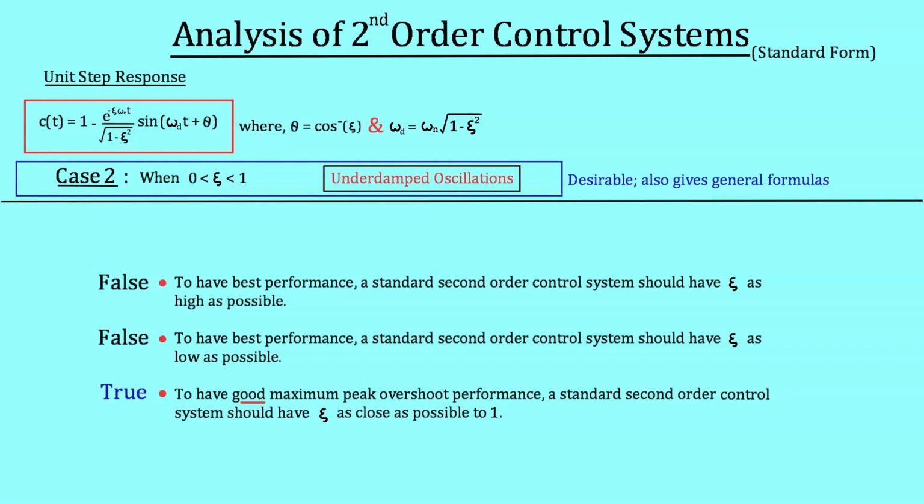If you are confused about the other parameters and what the ideal value should be, then let me tell you, the ideal output profile should look exactly like a unit step signal. And a unit step signal has all the parameters which we have studied in this lecture equal to 0. Rise time, peak time, maximum peak overshoot, delay time as well as settling time should all be 0. These are the ideal values, but remember, for getting these ideal values, we may require different values of zeta. Try yourself, consider different parameters and determine which value of zeta is favorable to have a smaller value of that parameter.